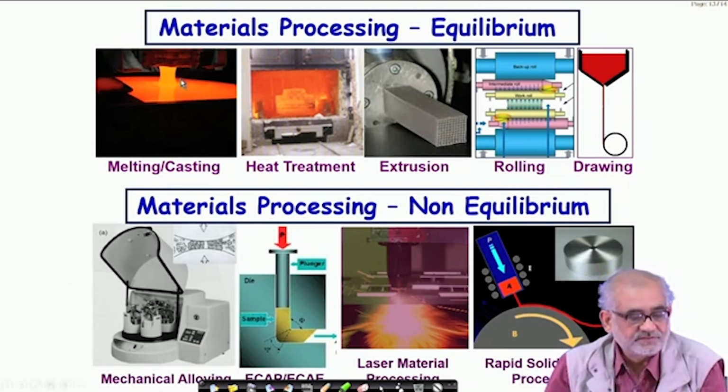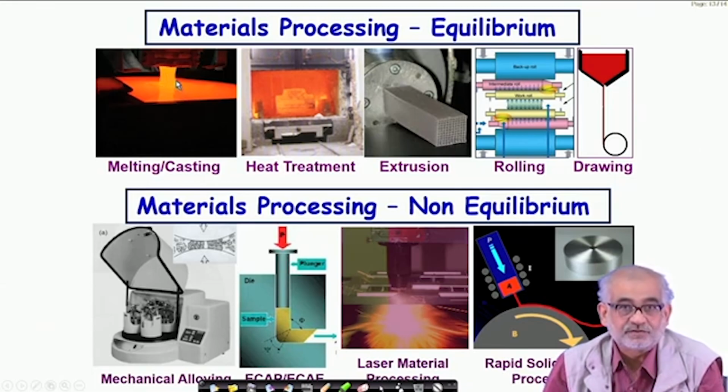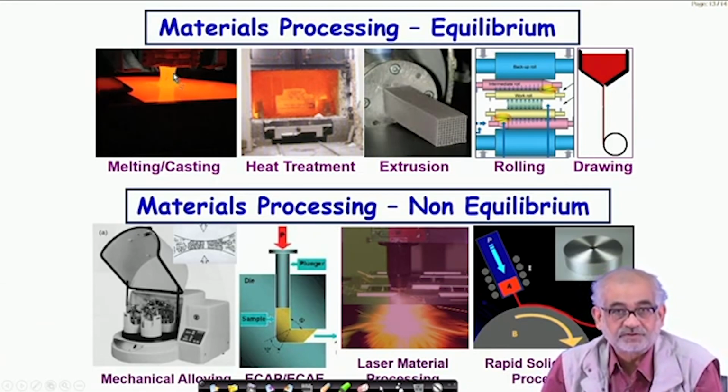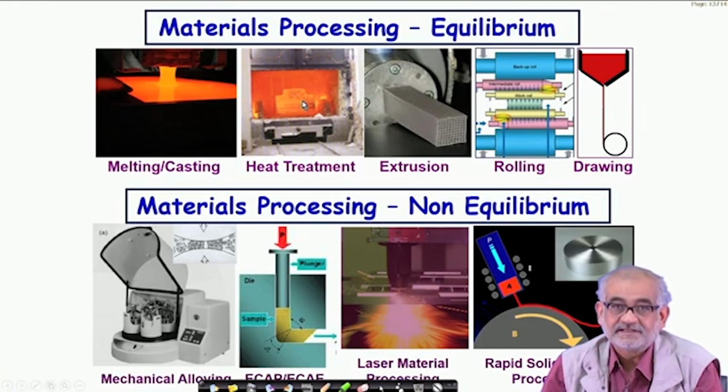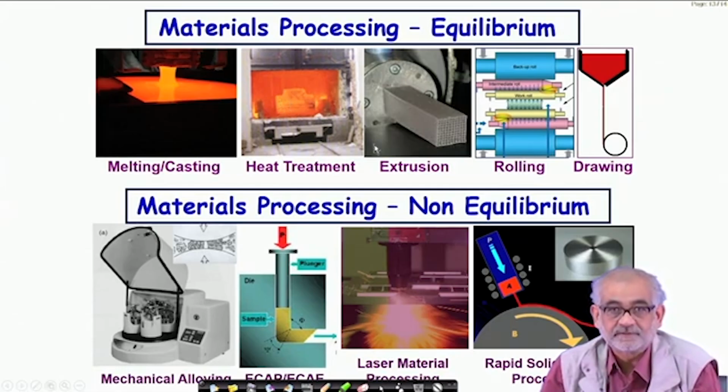Say for example, here what we are seeing is the pouring of glass. This is how glass, when brought to the liquid state, can be gradually cast, and a structure out of silicate glass or non-silicate glass can be formed. This is how we can heat and then beat, and through such thermomechanical processing we can create certain solids of very specific shape, size and geometry.